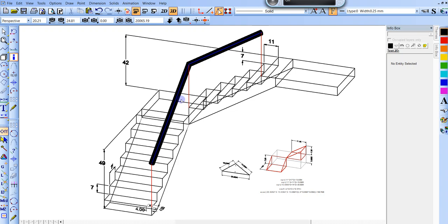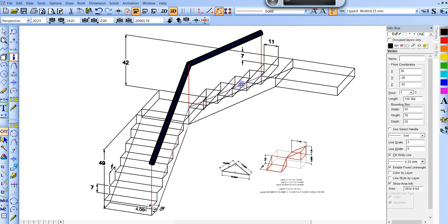There are two things that happen here. If you want that, you have to make sure that you put it in the right spot. The angle itself will be the same as this angle, right? Or just anywhere along the treads, like that. That's the right angle. However, that's not the right location if you're going to get your stairs designed. If that's where your stanchions were, right on the theoretical corner, that tread would be fine. So I'm going to touch base on that first.